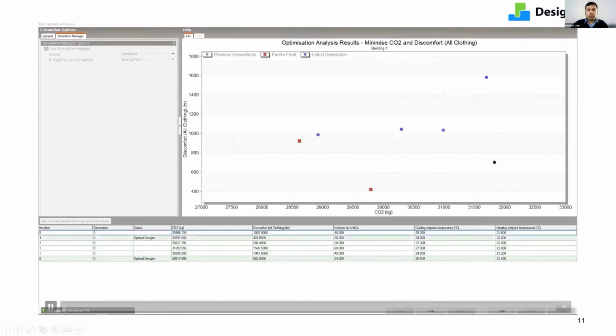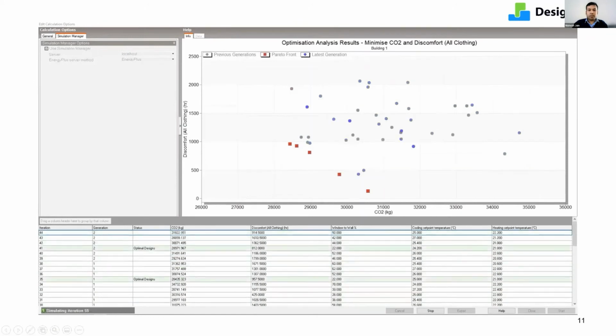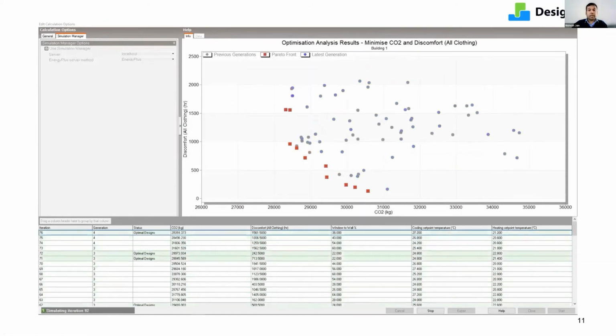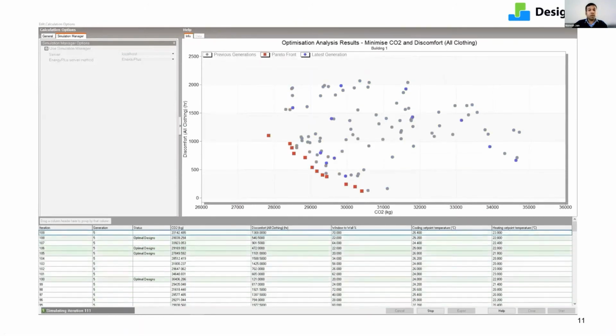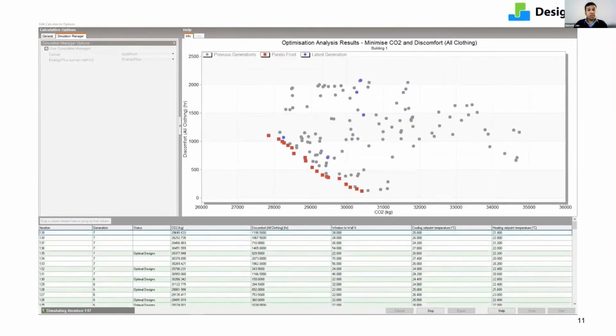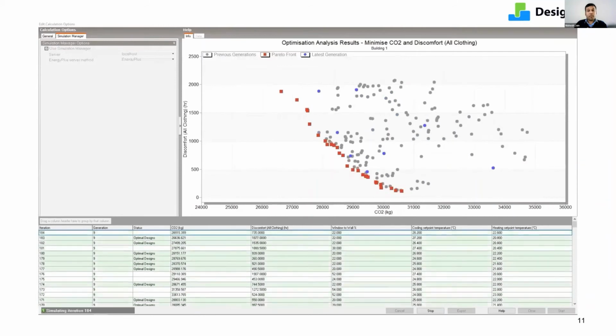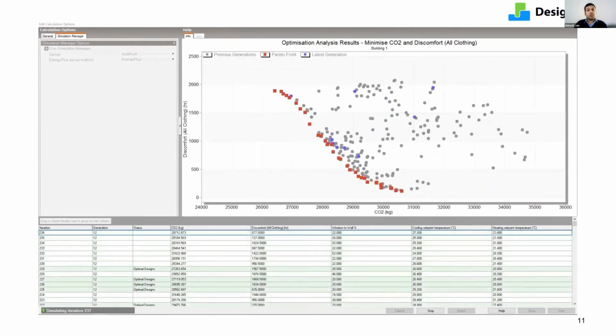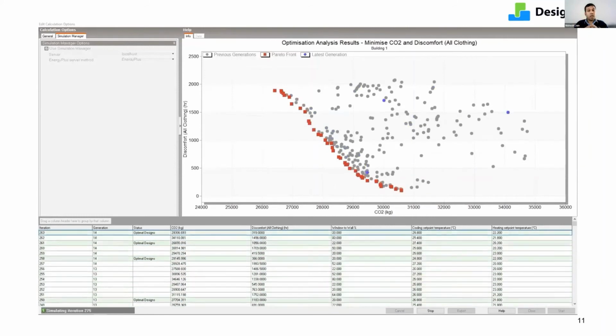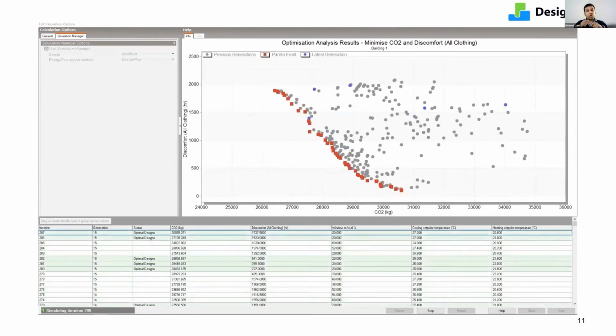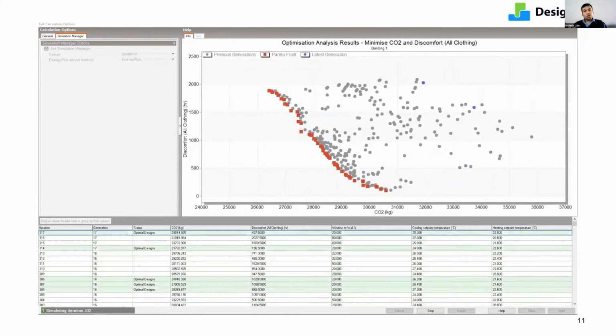This is a short sped up video that illustrates how a Pareto front develops for a small model. The design objectives are to minimize discomfort hours and operational carbon emissions, and individual simulations form the point cloud, and the algorithm selects the strongest solution from each batch, slowly migrating towards the origin as the objectives minimize.